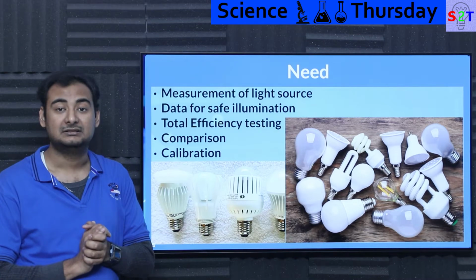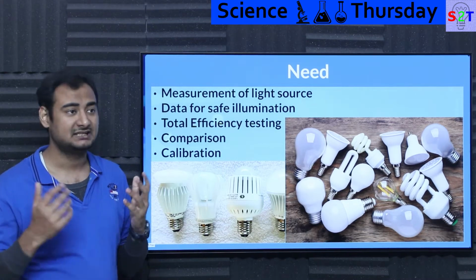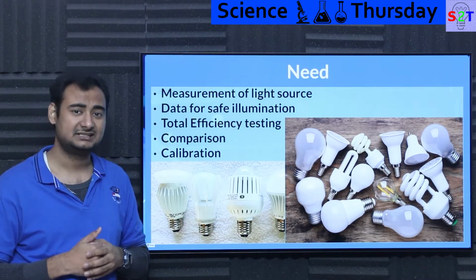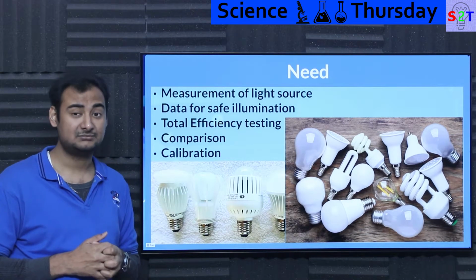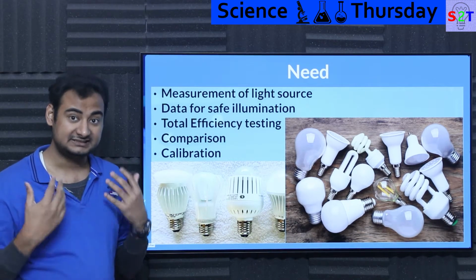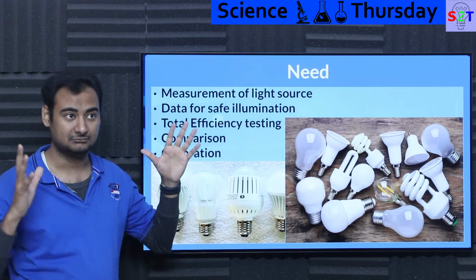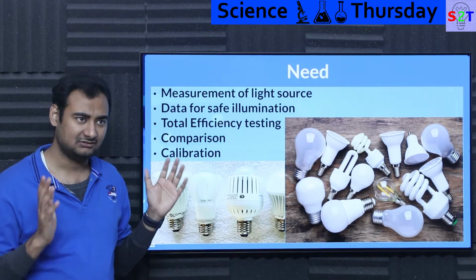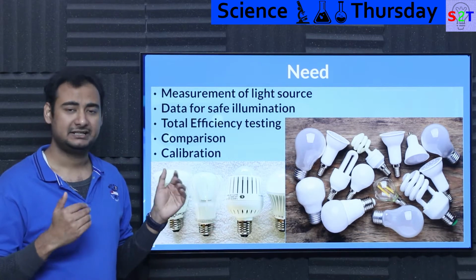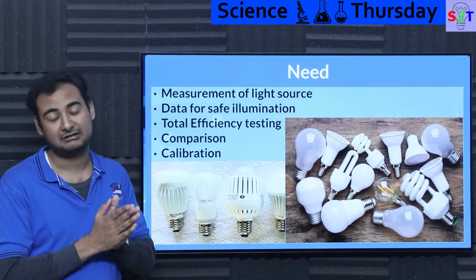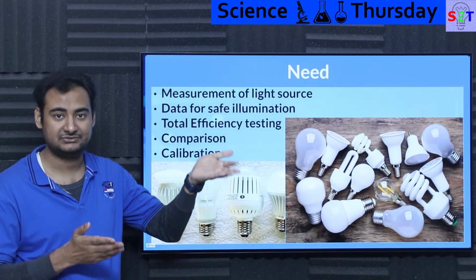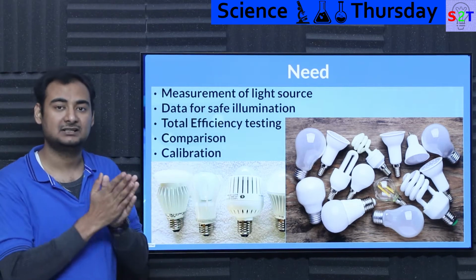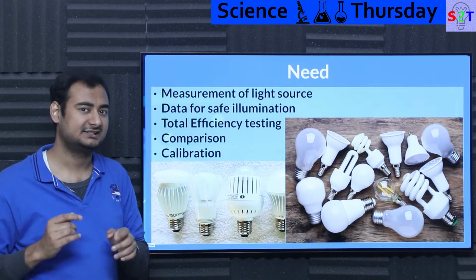For example, till this point many people assume LEDs are very efficient, as in like 90%, but the reality is they are very close to 50%, and some are even lower than that. This is the prime reason that when you watch any major company dealing with indoor farming, they will never use white light, they will always use monochromatic light. I never understood that, but now I understand that a monochromatic LED is used in white LEDs, and then the light goes through a phosphor layer that emits the light. But here's the thing: the phosphor layer is not 100% efficient.